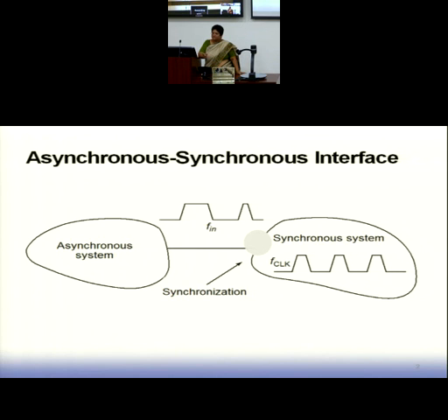So if something comes within that window of T setup hold, as you said, metastability results, because your output might not have reached the full logic levels. Since within that period the system state is not known, input state is not known, so this value is unknown. It is something which is not very clear to us.